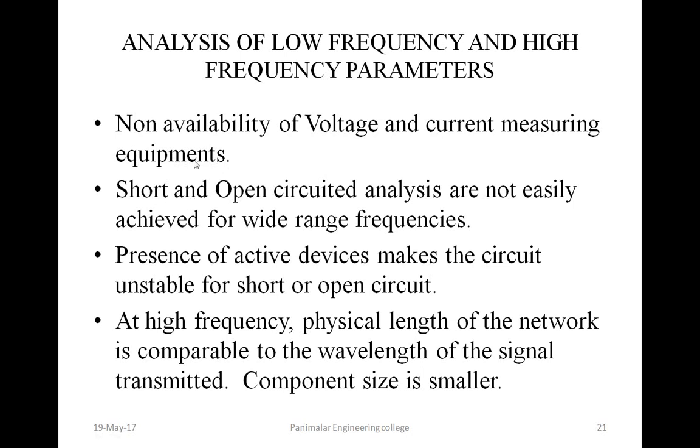And the other problem is with respect to the short circuit and open circuit, because in high frequency a short circuit or open circuit contributes to standing wave ratios. As the frequency is increased, the effect of standing waves is going to be greater. So we cannot make analysis using short circuit and open circuit as in low frequency circuits. So short and open circuit analysis are not easily achieved for a wide range of frequency. Open circuit is much more difficult.